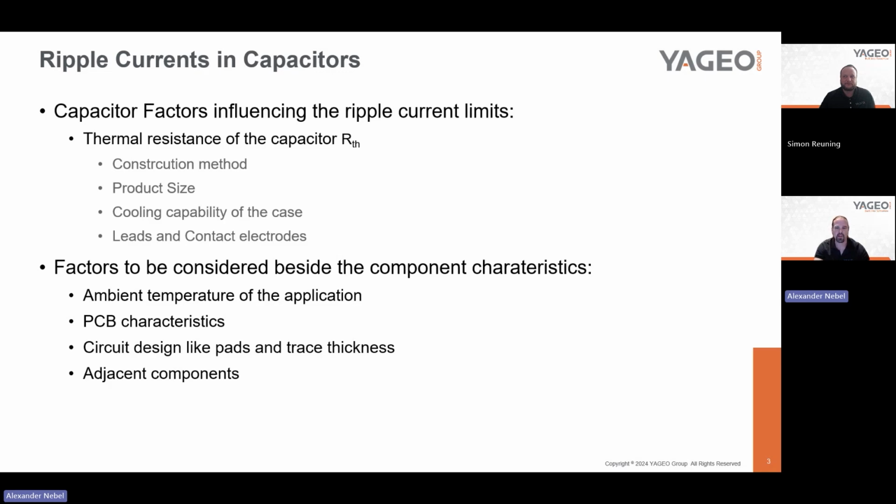Especially for film capacitors and aluminum capacitors, the self-heating is an important topic as too high temperatures may decrease the maximum lifetime. As always, the rule is the same here: a capacitor, like any passive component, should never be used outside its specification.